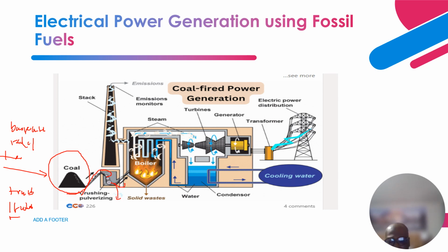The coal comes in the form of rocks, miniature rocks, and a little bit close to powder. So it has to go through total crushing, where the miniature rocks and quite close to powdery form are totally crushed into fine powder. And this is achieved by a PA fan. Basically, it goes through a pulverizer.